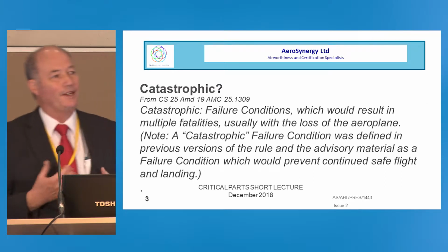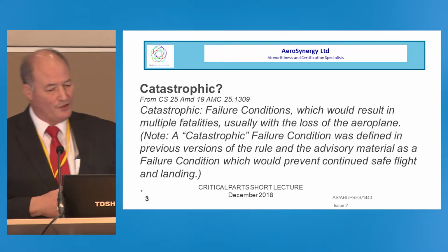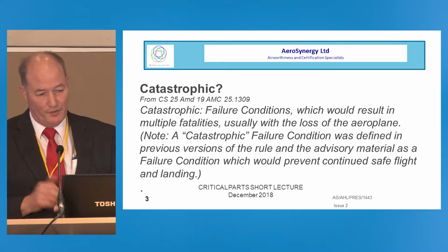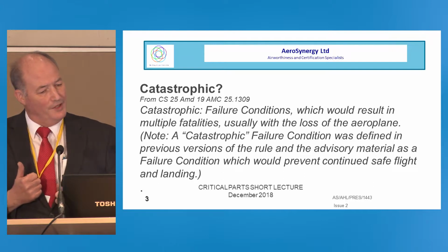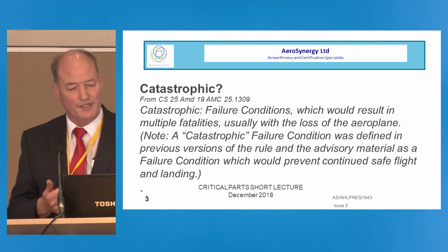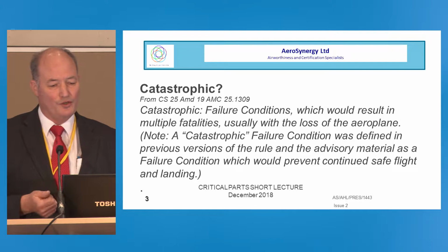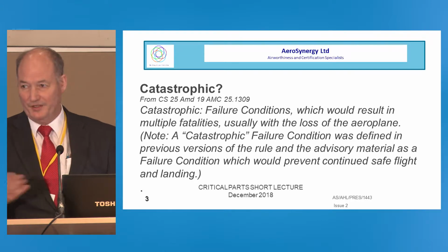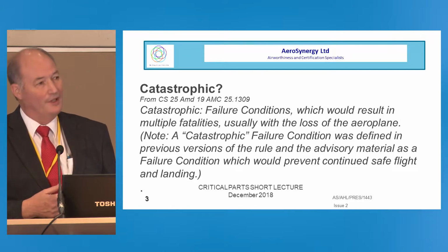So what do we mean by catastrophic? A catastrophic is defined, funnily enough, in CS25.1309, as a failure condition which would result in multiple fatalities, usually with the loss of the aeroplane, or in this case, the helicopter, the aircraft.